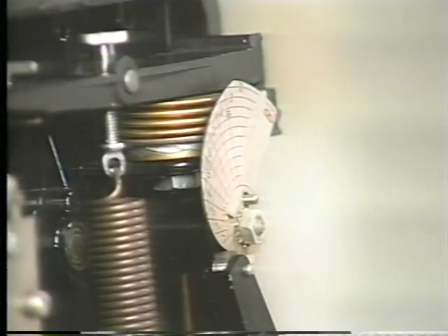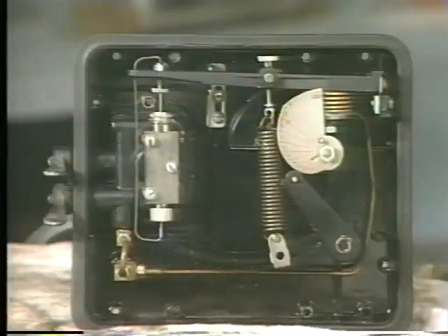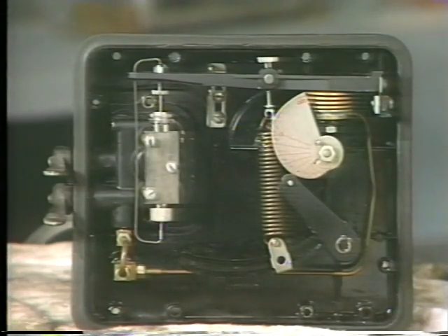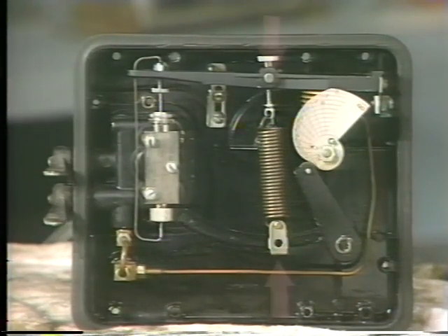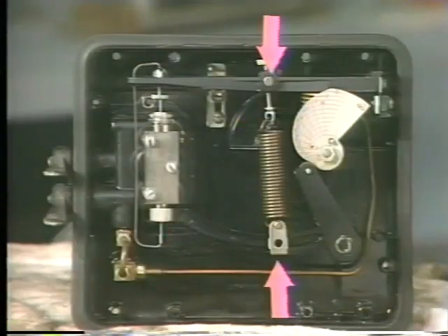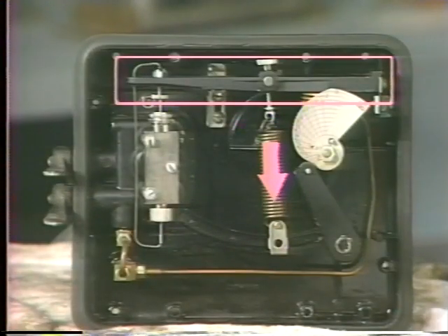When the cam rotates, it pushes against a little roller, which is called a cam follower. This roller, or cam follower, is part of the device which is called a spring beam assembly. When the cam rotates, it pushes against the cam follower, which causes the spring beam assembly to rotate. The spring beam assembly is different than the balance beam. Both beams are connected by a spring, so when the spring beam assembly moves, the motion is converted to a force, which is the force of this spring pulling against the balance beam.